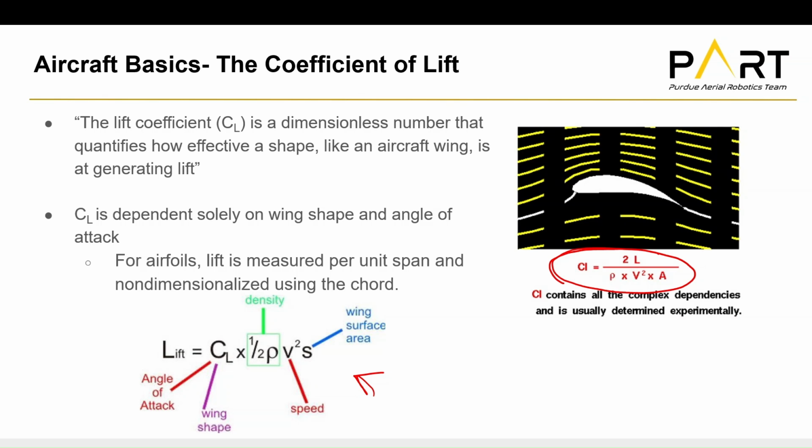Aerodynamics is stupid. Nobody knows what they're doing. And to be honest, the best way you can figure out the lift for a plane is by, at some point, sticking something in a wind tunnel and doing your own empirical gathering of data. So we've stuck a plane into a wind tunnel. We've calculated its CL by using the area of the wing that we have and the amount of lift that it's generating. And now we have the CL number for a plane.